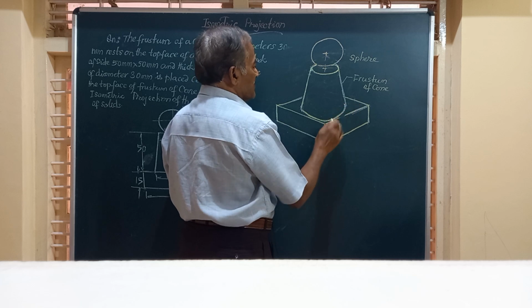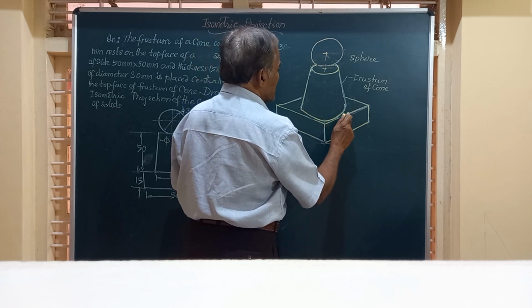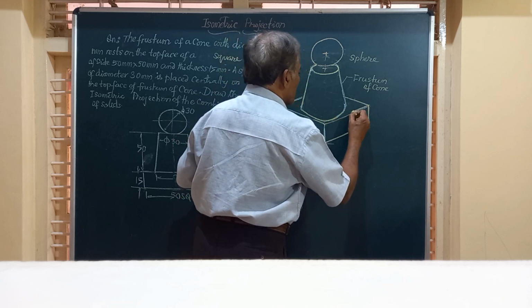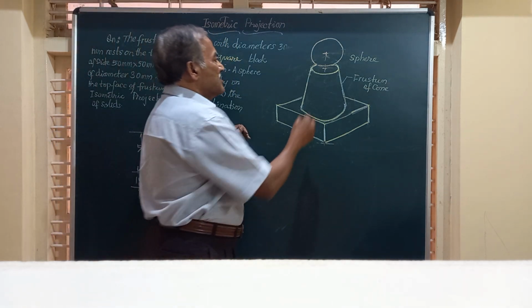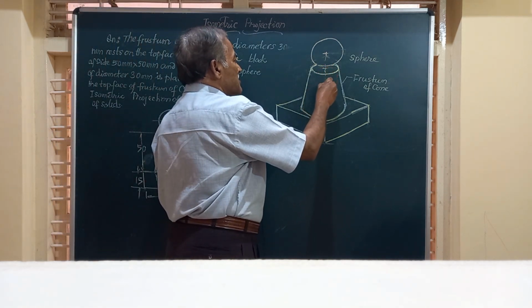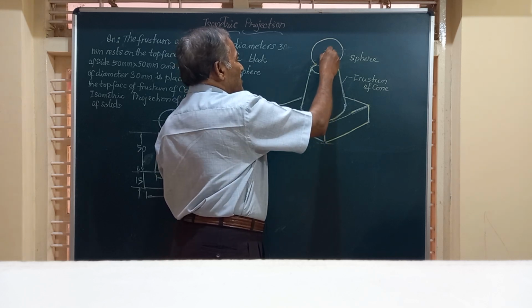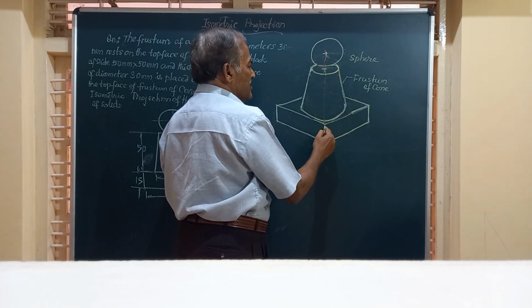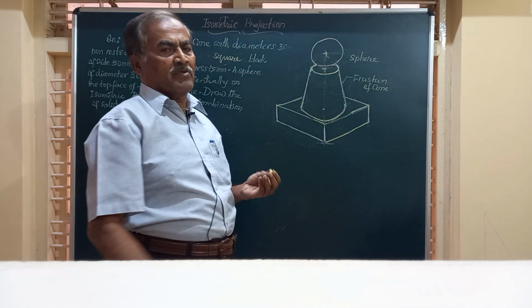And friends, this is how the projection of this block will look. Friends, you should also remember that the axes of this square block will all fall on the same line. That is the center of the circle, the center of this ellipse, and the mid height of this block, all will fall on the same line.